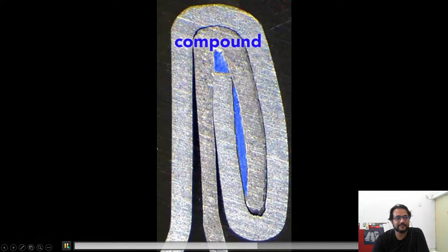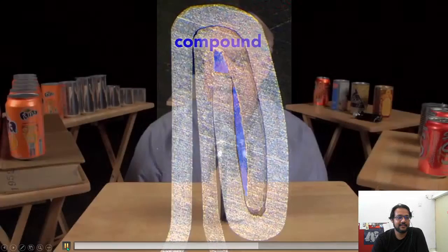The sealing compound is applied as a liquid and hardens to form a gasket. The end, attached immediately after the can is filled, traps gases inside the can to create pressures of about 30 psi, or 2 times atmospheric pressure. In soda, carbon dioxide produces the pressure. In non-carbonated drinks like juices, nitrogen is added. So why is a beverage can pressurized? Because the internal pressure creates a strong can despite its thin walls.